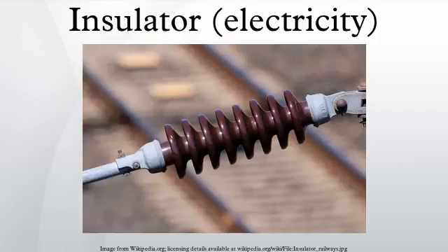Windings that use thicker conductors are often wrapped with supplemental fiberglass insulating tape. Windings may also be impregnated with insulating varnishes to prevent electrical corona and reduce magnetically induced wire vibration. Large power transformer windings are still mostly insulated with paper, wood, varnish, and mineral oil. Although these materials have been used for more than 100 years, they still provide a good balance of economy and adequate performance. Bus bars and circuit breakers in switchgear may be insulated with glass-reinforced plastic insulation, treated to have low flame spread and to prevent tracking of current across the material.